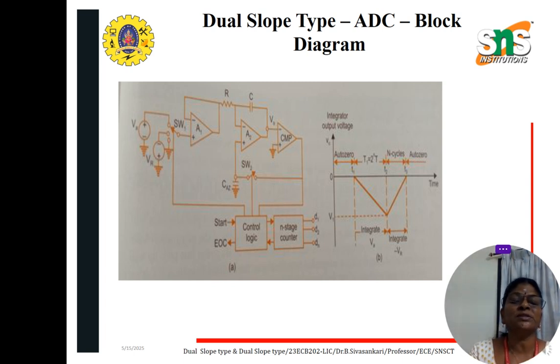So first through the switch we are giving two input voltages and we are just starting the conversion. The known input voltage and the reference input voltage are always vice versa. If the known voltage is 0, our reference voltage will be 1. So these input voltages will be given. First the high impedance buffer will convert the signal, high into low and low into high, and then it is passed to the integrator circuit, where the integrator defines the difference between the two input voltages.